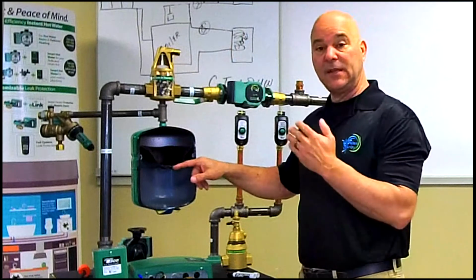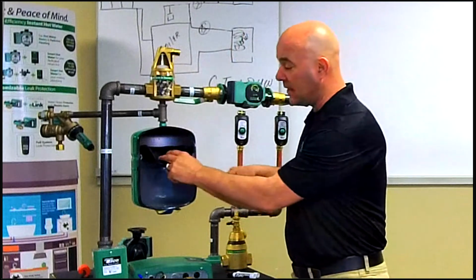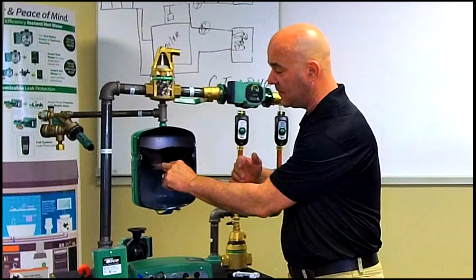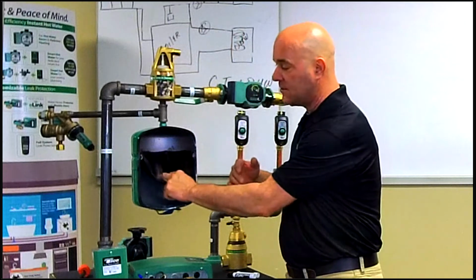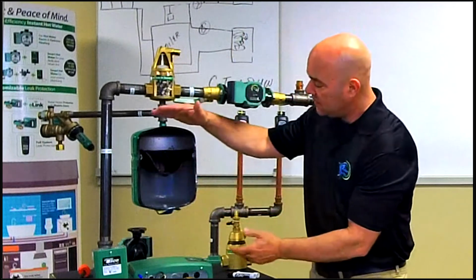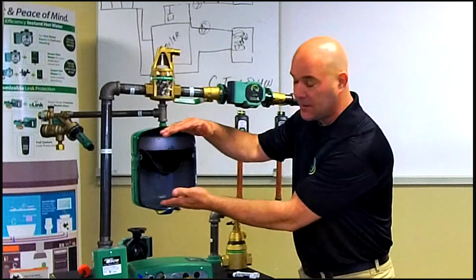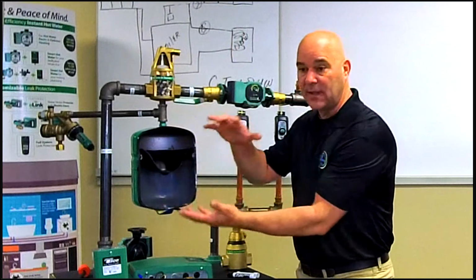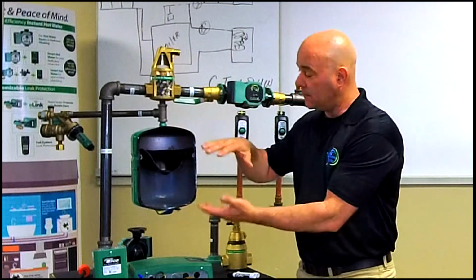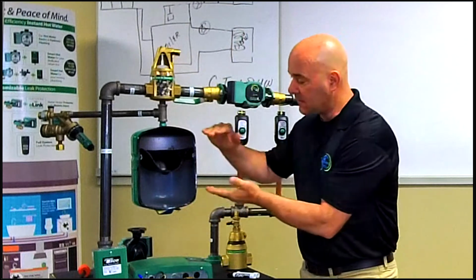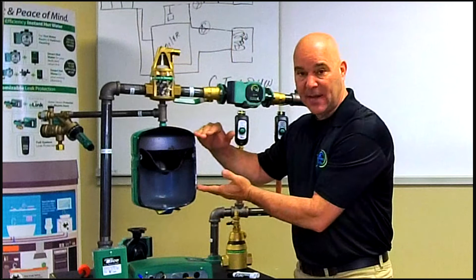Now I'm going to heat the water up in the system, and I need to expand that water. The water's going to expand. It just happens when we heat it up. Now I'm going to start to push down this rubber diaphragm, and you can see here I'm going to start to stress that because the pressure on the top side is greater than the pressure on the bottom side, and the rubber diaphragm is going to take all the abuse. And this tank will probably fail prematurely because I don't have equal pressures on the top and bottom.